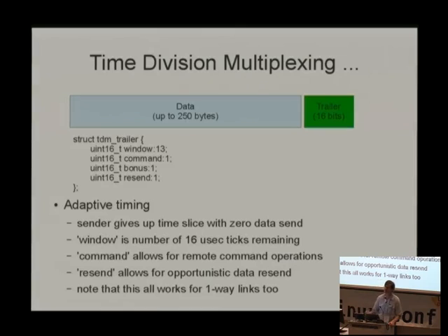And the biggest extension was the addition of this command bit, where you know the AT command set controls the local modem. Well, the RT command set for remote controls the remote modem. And anything you can do with the AT command set on the local radio, you can do with the RT commands on the remote radio. So RTI, RTS7=15, whatever, all of that is available, which is extremely useful when there's a plane flying about and you want to adjust the parameters, the error checking that it's doing, and you don't need to land the plane and go up with a USB cable or whatever. You can just reconfigure it remotely while it's flying around, which is really handy as long as you get it right.